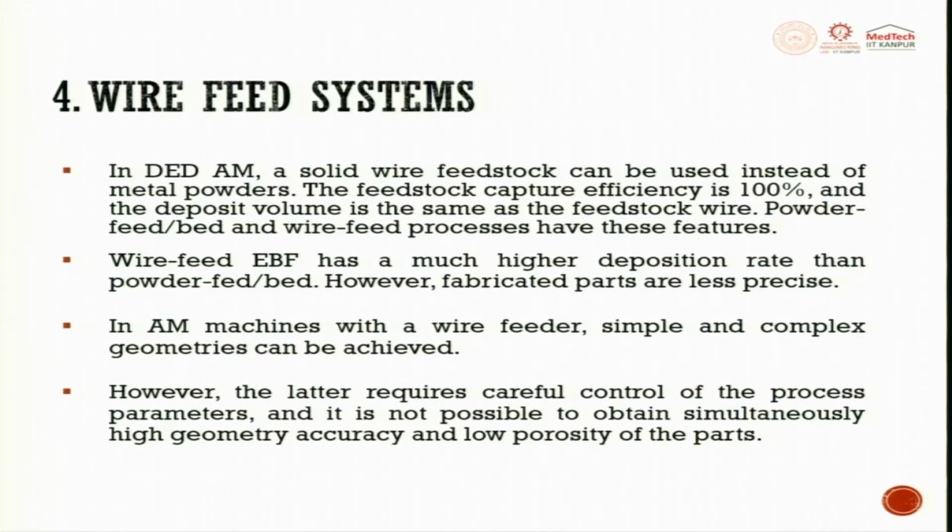The last process which we are discussing is going to be the wire fed system. In directed energy deposition additive manufacturing, a solid wire feedstock can also be used. Powder can be used, wire also can be used instead of metal powders. Why? Because of this, all the problems of agglomeration and improper feeding, we converted into a wire. Wire can be easily extruded.